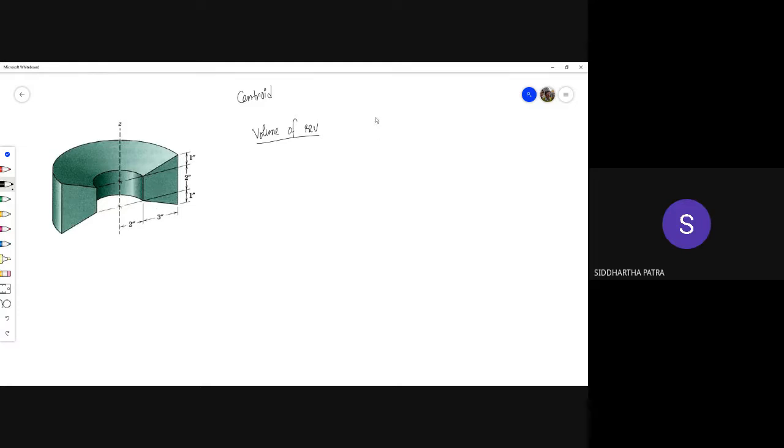But I would suggest, except for a rectangle, for which it is exactly in the middle, so h by 2 and b by 2, and for a triangle, and not necessarily a right angle triangle, any triangle, the location of the centroid perpendicular to the base is 1/3 away from the base.